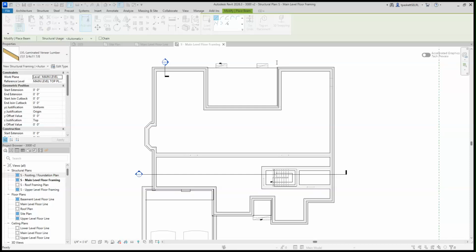And I'm going to take off the 2 because I don't want the notes copy. I'm going to change it to a 3.5 inch beam, so it matches my wall thickness where my studs are with interior studs. So I'll match that thickness. I hit OK. And there, I'm going to come down here and do the same thing here. Change the size, 3.5, and apply that and hit OK.